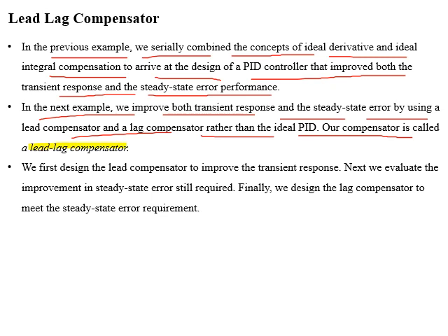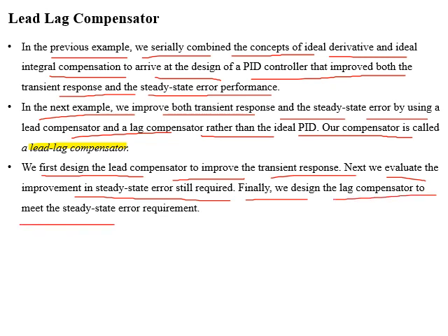We will first design a lead compensator to improve the transient response. Next, we will evaluate the improvement in steady-state error still required, and then we will finally design a lag compensator to meet the steady-state error requirements.